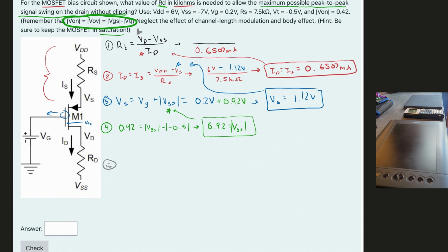Now, this can be found, I believe, a little bit earlier in the notes, and the way we would write this is that we have our VDS, the absolute value of it, and that's for PMOS, which is what, again, this is, which is greater than or equal to our absolute value of our VGS minus our VT, and then P for PMOS.